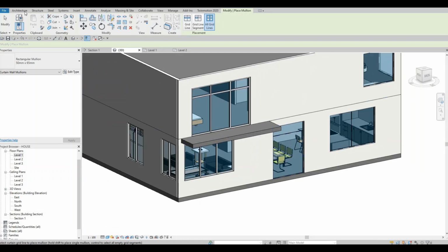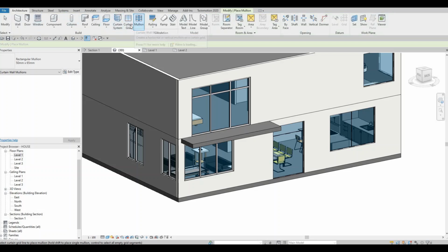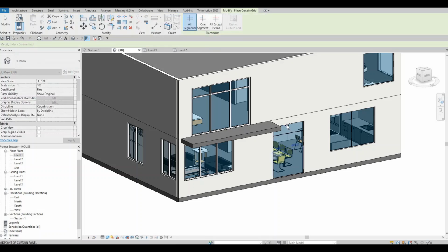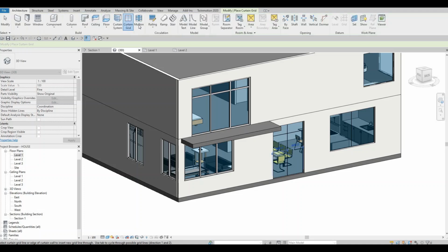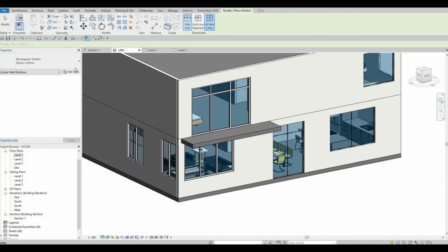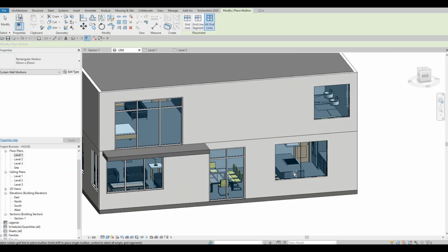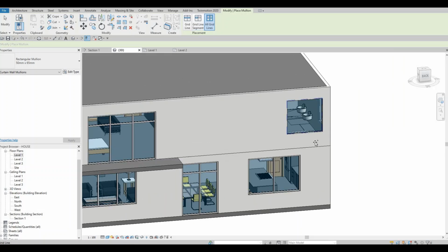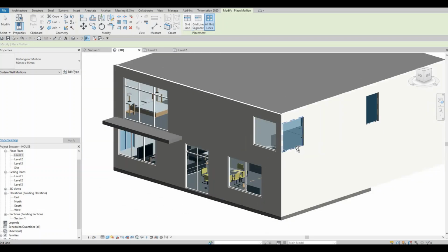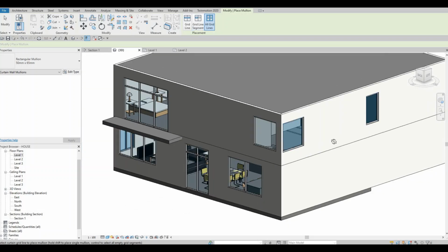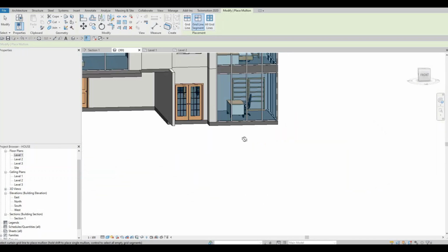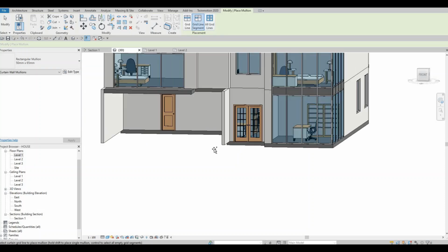Here, I'm just gonna go back here and add in a curtain grid, which is half, and then go back again to mullion, all grid. I forgot that we have another door here as well. Okay, now everything looks good.